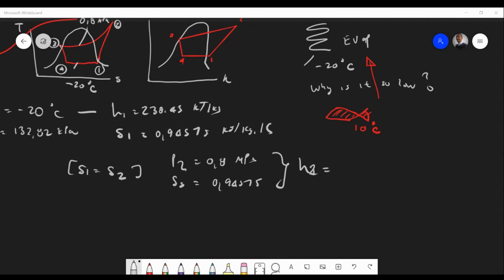I'm deliberately doing this process over and over, so you can get good practice now. Very important. Some students didn't even know the process. It's isentropic. You cannot lose marks in this chapter. So you're going to go to table A13 again, find the corresponding pressure, and I wanted you guys to interpolate for me. I'm going to just snip the table for you again.